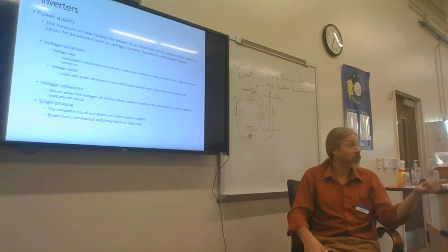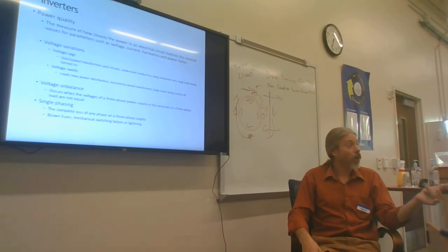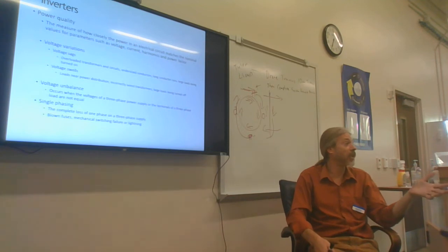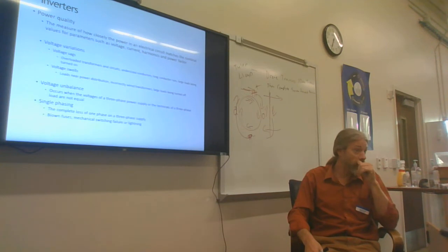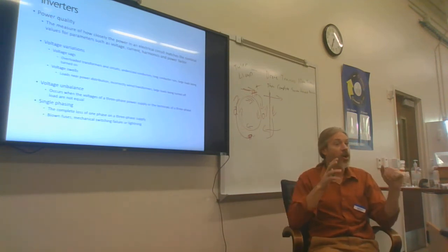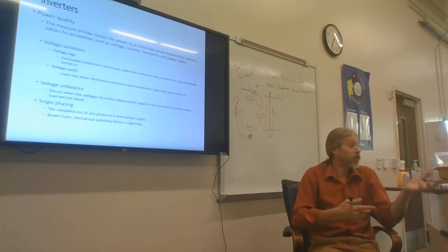In the mornings when factories start, when shift changes happen, or when we reach certain temperatures and AC or backup refrigeration units begin to kick in. Say you're a factory and it's okay to work up until 80 degrees, but your parts have to stay under 80 degrees. Suddenly it gets to 80 degrees and a large AC system kicks on. That non-normal large load could affect the other loads in the building and cause problems for them.